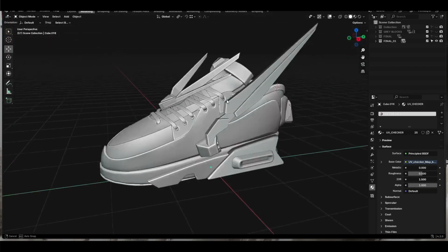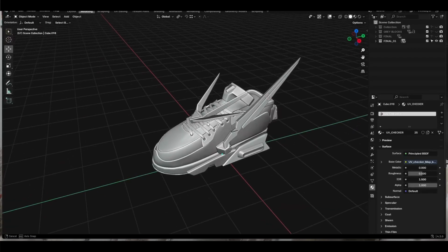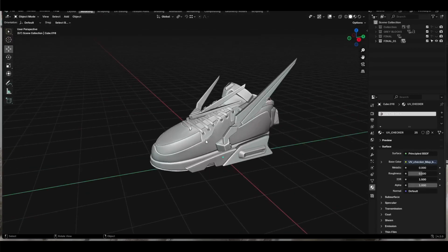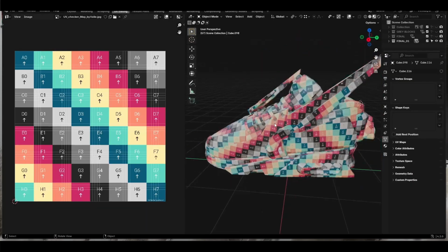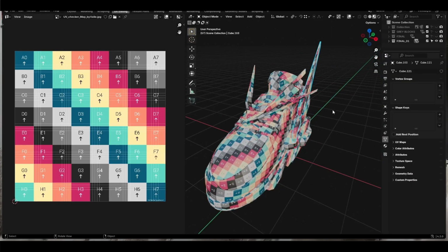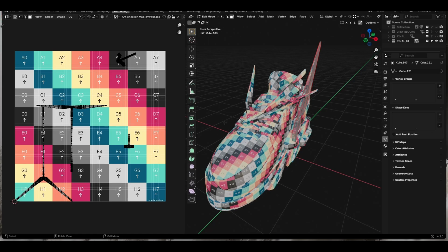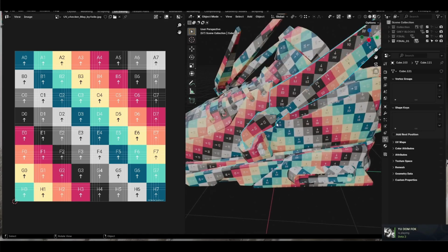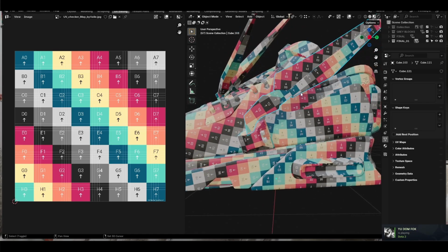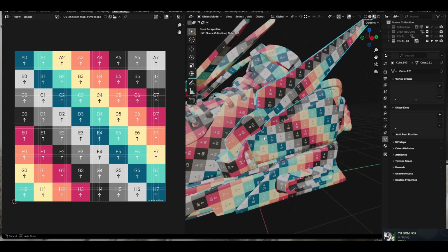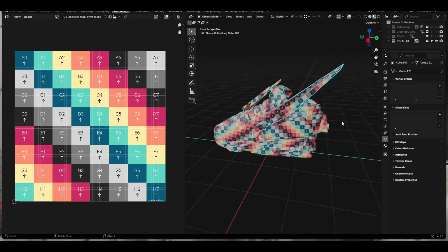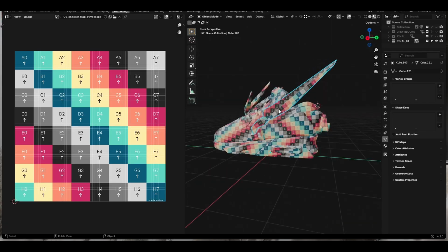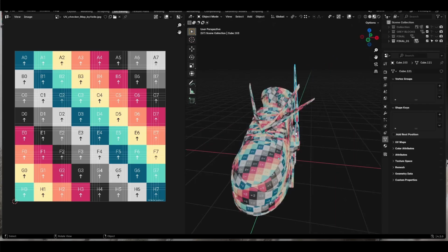The reason why I UV them first is that once we start UVing everything, every time we duplicate parts, it will automatically duplicate the UV as well. So that every time we texture this, it will also automatically texture the other part, like the duplicated parts for this. And we don't need to texture them individually, you know.